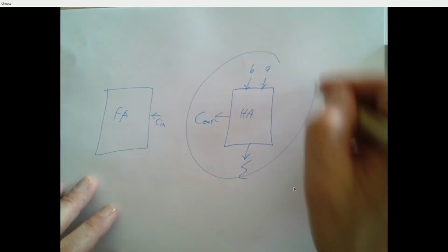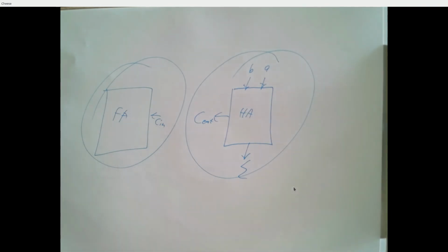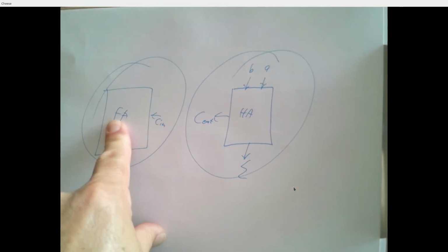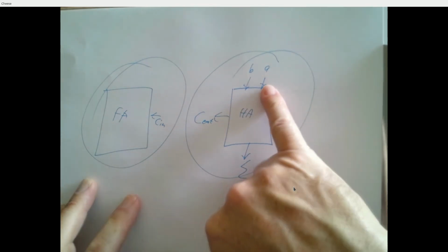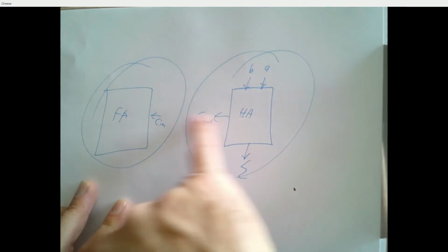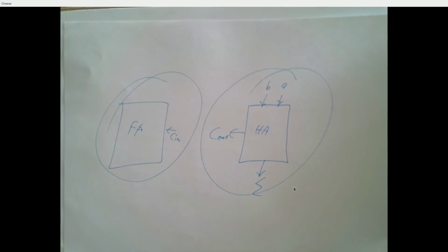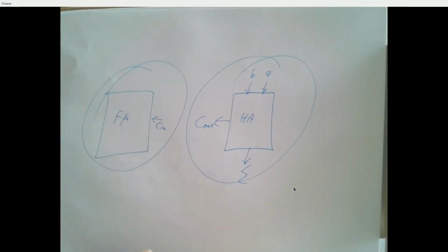But once you have this available to you, right? Imagine you're trying to build a 2-bit adder. Well, you go into your parts box and you open it up, and there's a chip, and it's labeled half adder. And it's one of these things. And you have another chip, and it's labeled full adder, and it's one of these things. Very easy to build your adder now. Take your full adder, connect 2 switches here. Take your half adder, connect 2 switches, tie that to that. Put these 3 into your LEDs or your 7447, and you're done, right? Most of the wires and chips on your board were actually building this thing and this thing.